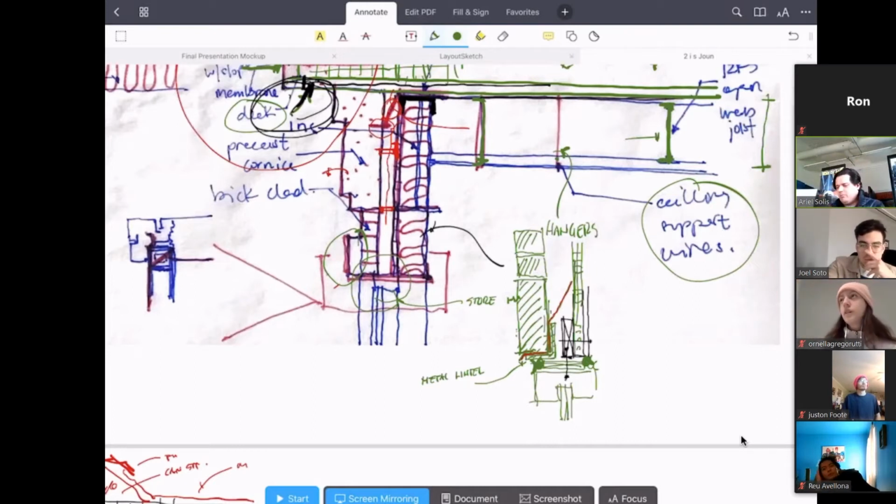And once that happens, they come with a sealant outside over that window, and that basically hides the backer rod, because that's like an insulation piece. Then I will have my metal stud right in here, depending on how big this wall is. The next thing I need to worry about on the metal stud is that I may need a header for that metal stud inside. I don't know how big the span of that window is. If it's 6 feet, 7 feet, whatever, I may have to have a header.